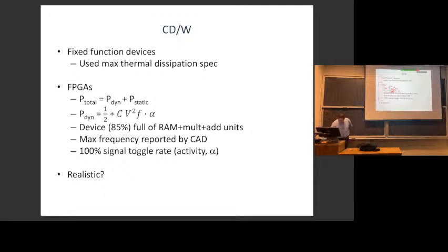The total capacitance is basically all the capacitance that has signals changing, which you kind of have to get from the device manufacturer. You don't know that, but it's some number for that chip. And how often you're charging and discharging it is once per clock cycle, at the clock frequency. A clock edge happens, and now things start changing, so you start charging and discharging the capacitances inside your circuit. But you don't usually charge and discharge every single gate. So this alpha is how much of your logic is changing state in any one cycle.